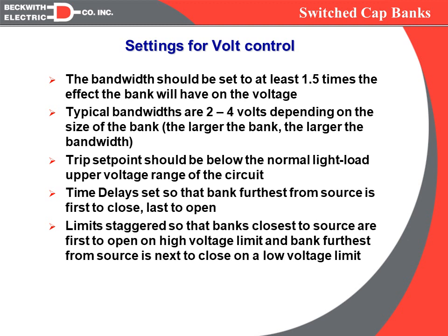So our limits have to be time delay coordinated just like the regular operation, and it's got to be done in the same order. So on a high voltage limit, the bank closest to the source will be the first one to open. And on a low voltage limit, the bank furthest from the source will be the first one to close.